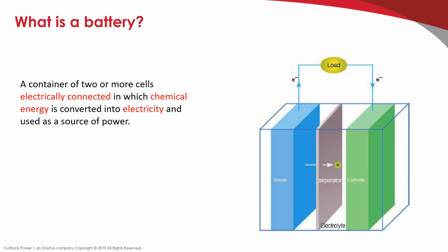For lead acid, this is usually called a 2-volt cell because the cell voltage for lead acid is 2 volts. It varies between chemistries, and it's based on the potential chemical energy between the two electrodes. So if it's lead oxide and lead, that ends up being about 2 volts. It's a little over. For lithium, it's about 3 volts. For nickel cadmium, it's different from that. And all that's based on the electrochemical potential between the electrodes.